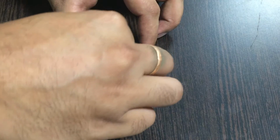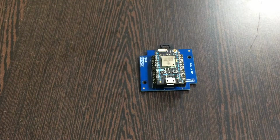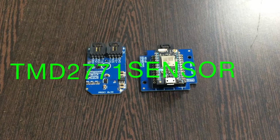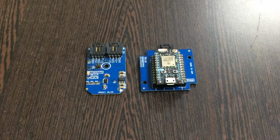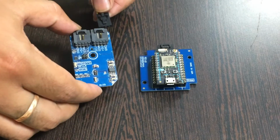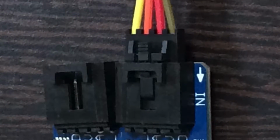Now gently press the particle photon over the I2C shield and make a connection. The next thing we require is our sensor, the proximity and ambient light sensor TMD2771. Now this here is a connecting cable. Make the connection between the cable and the sensor, and make sure that the brown wire of the cable is connected to the ground terminal of the sensor, and likewise on the I2C shield.